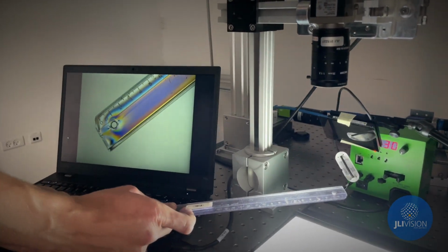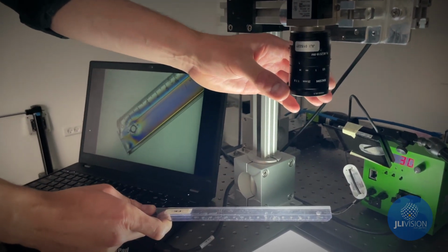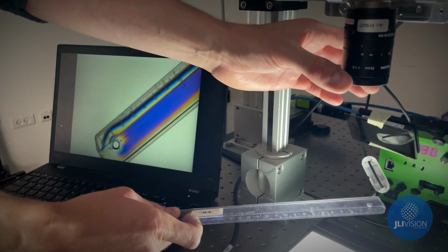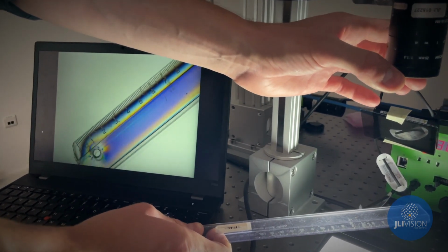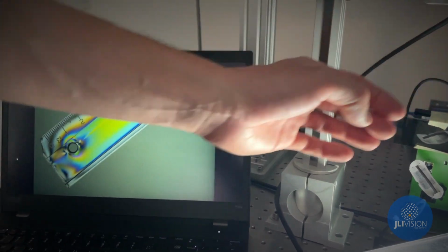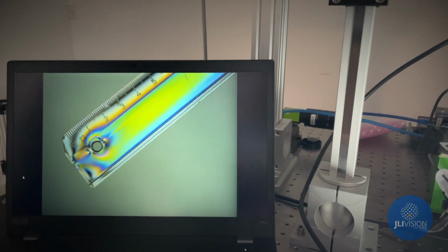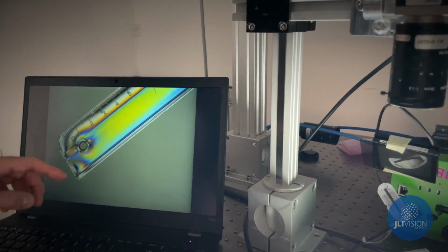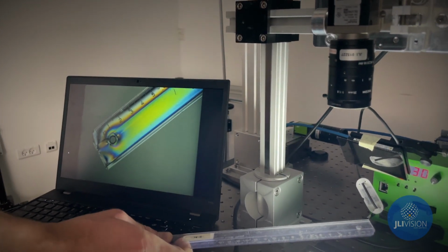Same goes for plastic. Say the plastic item during production has been pressured in a way that has left stress in the material. Those kinds of defects can be detected by taking a picture with a polarization camera. So by polarizing the light, we are able to see certain things more clearly and improve the result of the inspection we are trying to accomplish.